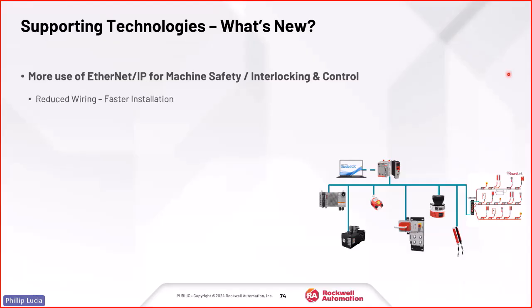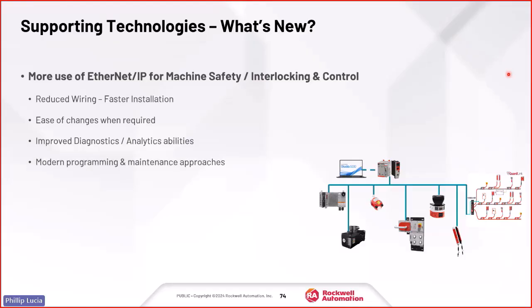We're seeing much more use of Ethernet for connecting our safety devices and safety controllers. Again, something we would never have imagined doing years ago, and getting all the benefits of industrial Ethernet, SIP safety, to reduce wiring and improve systems. Another development is that safety is so foundational now that we're including safety functionality for free, so to speak, in our Logix processors.